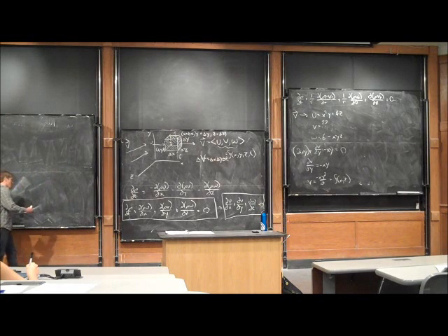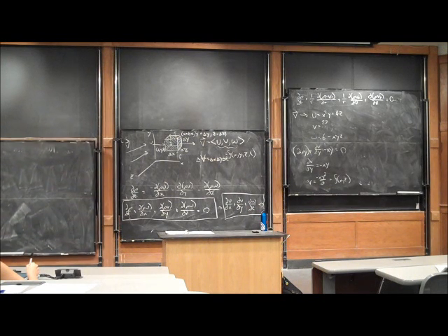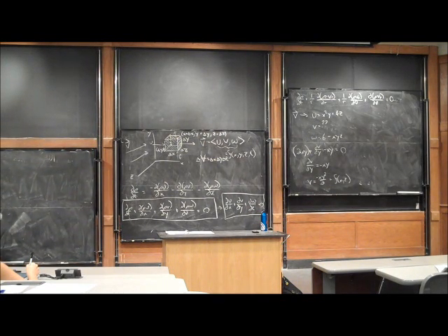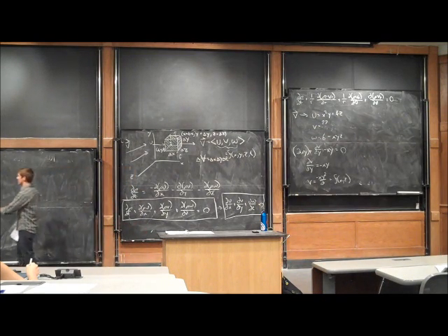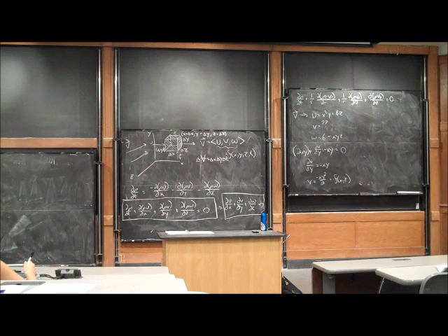So now I'm going to introduce the concept of a stream function. If we look at two-dimensional flow, we can classify it by velocity as a function of just u and v, assuming there is no z component of velocity. So if I look at continuity for a two-dimensional flow, I know that ∂u/∂x plus ∂v/∂y is equal to 0.